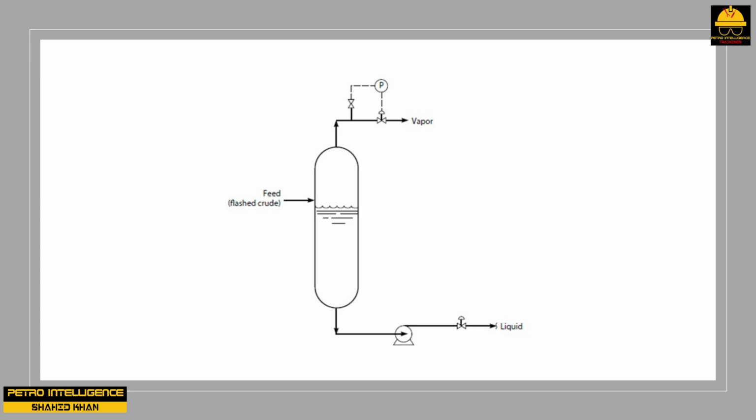A horror story. At a refinery, operators had to start up the pump shown in the picture. This was a new, flashed crude oil pump. It had never been run before. The refinery operators reported that the pump always cavitated on startup. They had raised the liquid level in the drum to within a few inches of the inlet nozzle. A higher level would cause entrainment of the black crude oil into the vapor outlet.